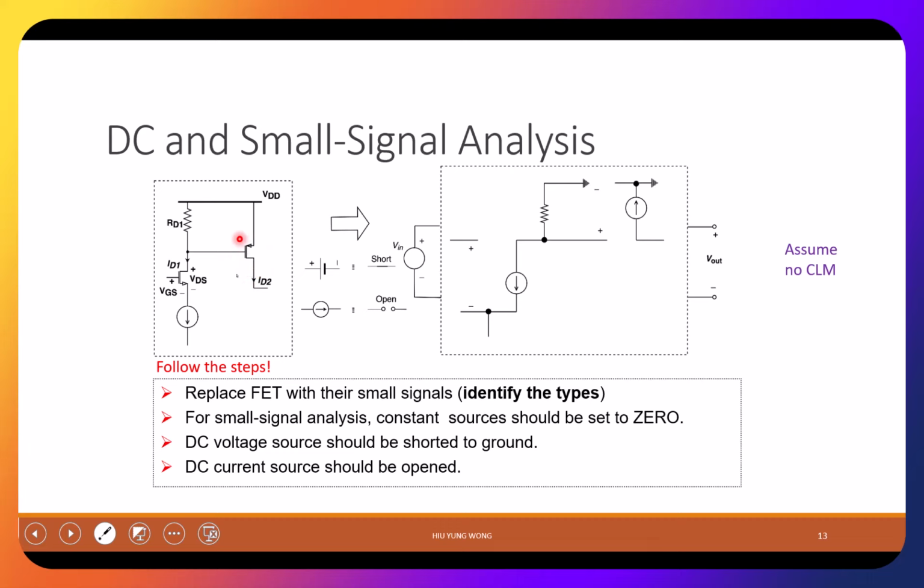But what type of transistor is this? PMOS. And that's why it's common source, because the source is here. If you try to solve it, it's very difficult to solve. But you can first find out the DC bias and then build the small signal model to solve the gain. Okay? So what do you need to do when you try to create a small signal model?